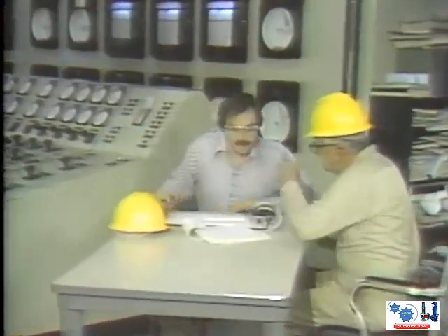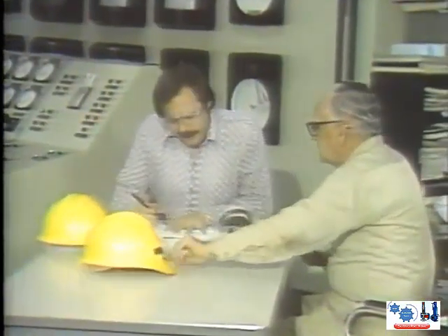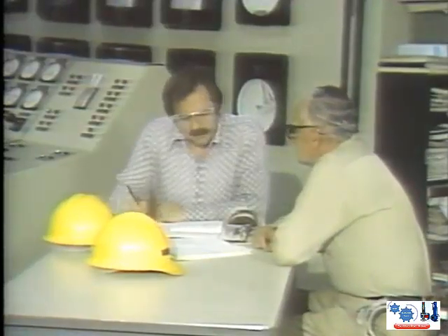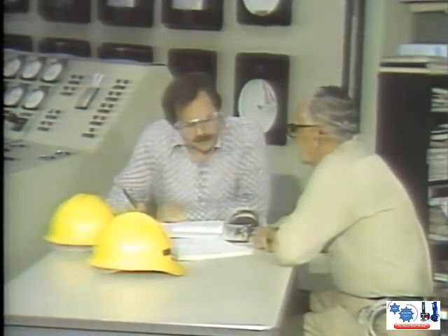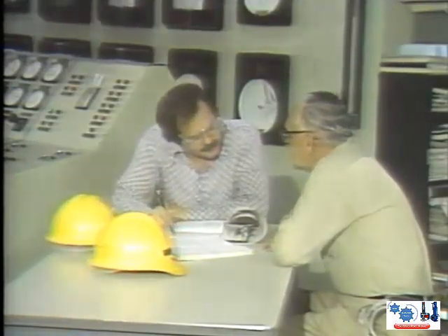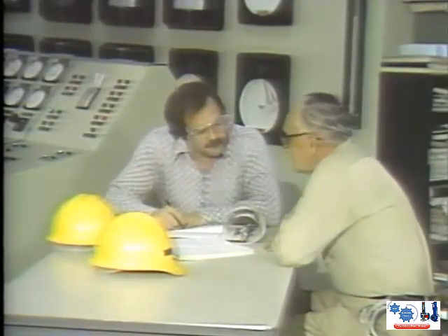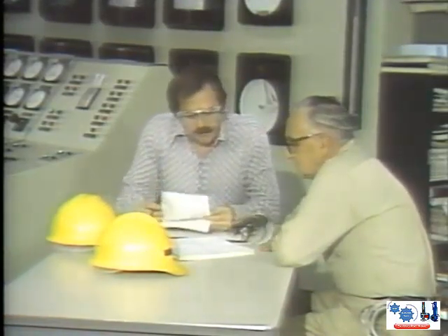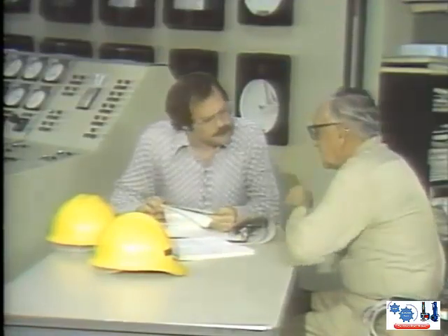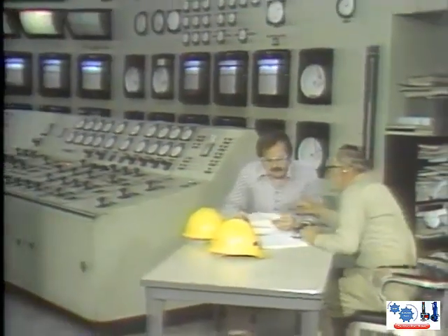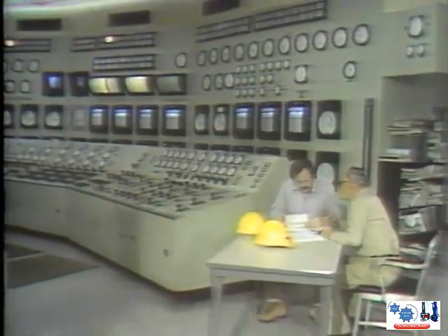Oh, I'm glad you showed up. I need to find out the enthalpy of steam at the outlet of the boiler. And I know that its temperature is 1,000 degrees Fahrenheit, and its pressure is 2450 psia, but I can't find it in either Table 1 or Table 2. That's because the process is superheated, so you have to use Table 3. Turn back over to the superheated Table 3.